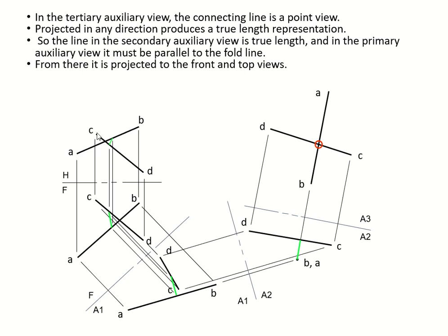Okay, see that top, there's also this little CD perpendicular to B. Kind of distorted, but it goes straight down. So if we trace back, this is your front view, and here is your parallel. So therefore this, right here, which is AB, is your true length. From true length, we've got the secondary auxiliary, okay.